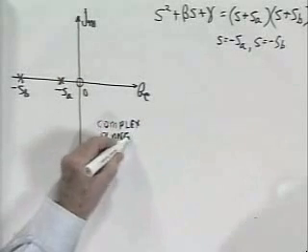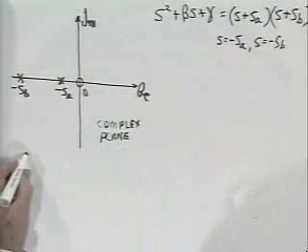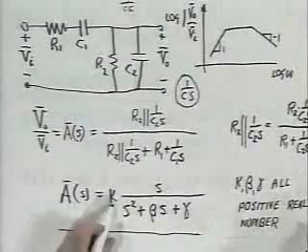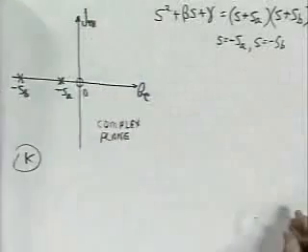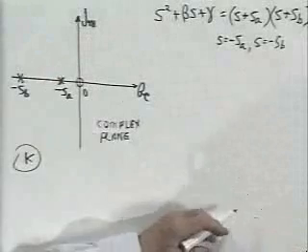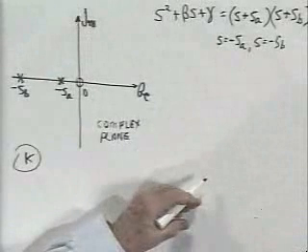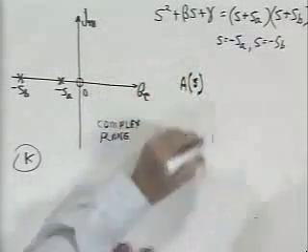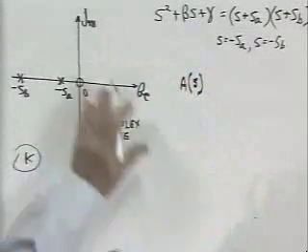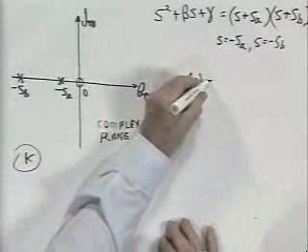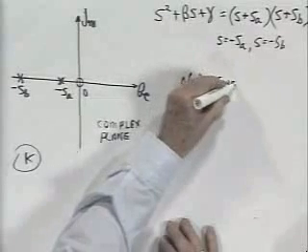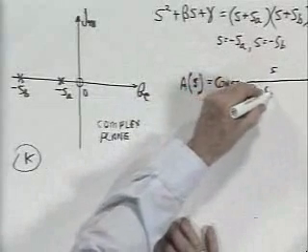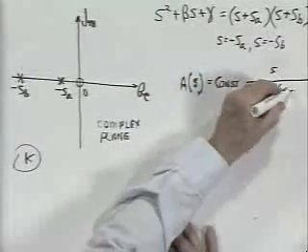And you recognize that except for the factor k, which appeared in this quadratic as a multiplier out front, this pole zero diagram describes completely the transfer function. That is, from the pole zero diagram, if I didn't know what circuit we were starting with, I could write that A of S is some constant, some scale factor, times S over S plus S_A times S plus S_B.